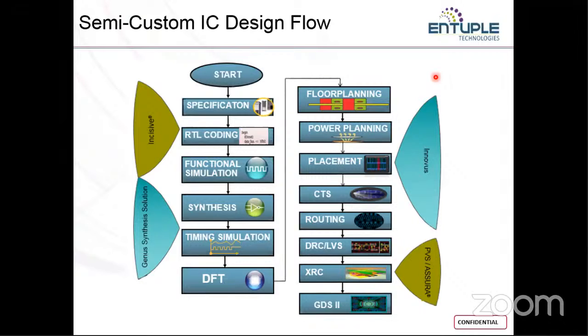This is going to be the space for my DRAM, or for my core processor. This is where I'm going to have my input ports and output ports, and this is where I'm going to have my USB port. Like that, you'll be deciding where each and every component or block of your design is going to be placed. That is what we call floor planning.